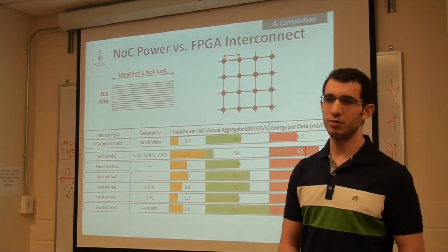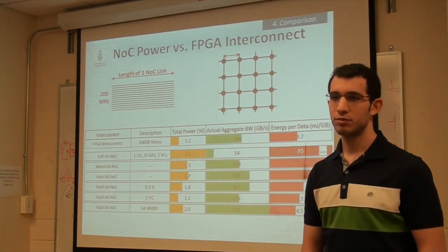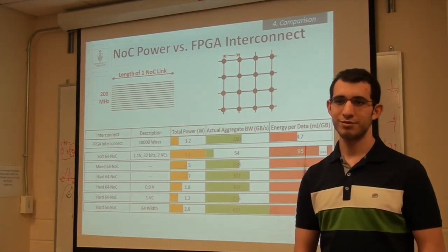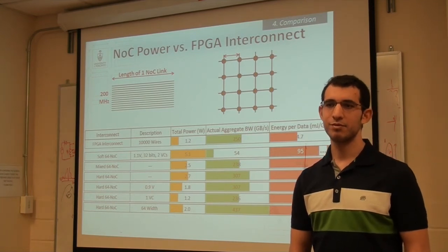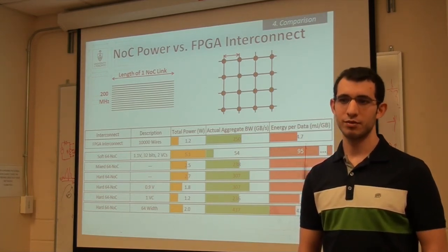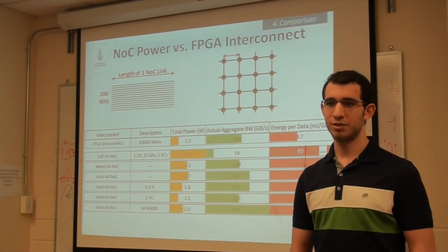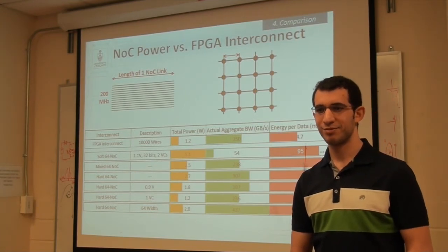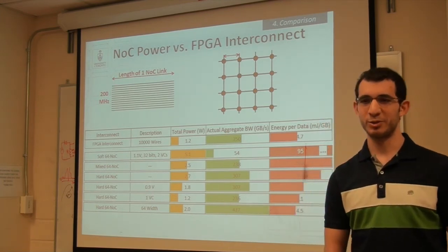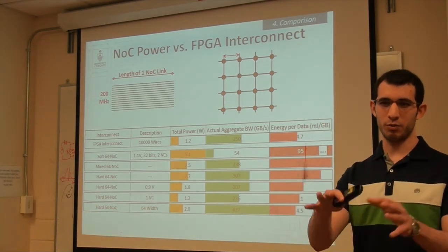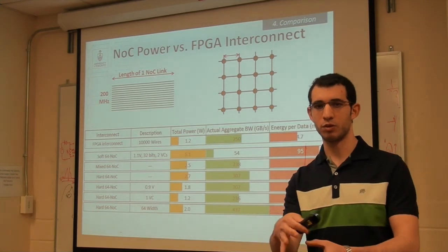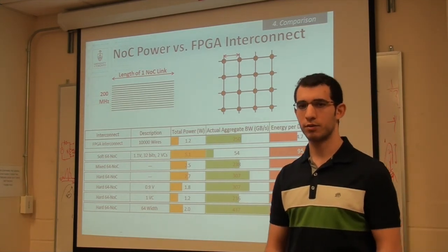Jeff? Yeah, just further on that, I think you could make that case about a lot of things that happen on FPGAs. If you've got multi-gigabit transceivers coming in where there's sometimes data, sometimes there isn't, there's FIFOs, there's clock domain crossings. Yes. The notion of deterministic latency is kind of already gone. No, yeah, you're absolutely right. So that's where we're starting, from the interfaces instead of from the actual core designs.